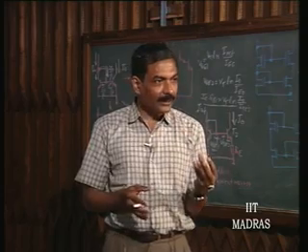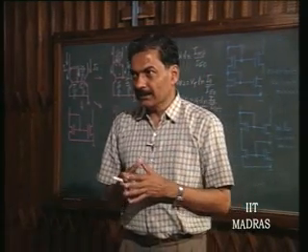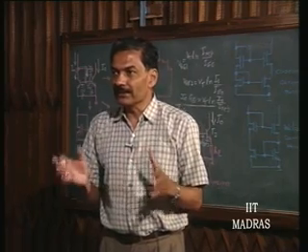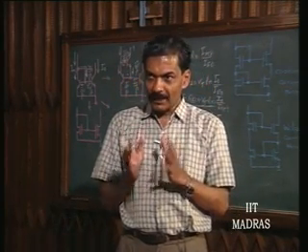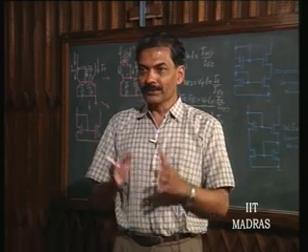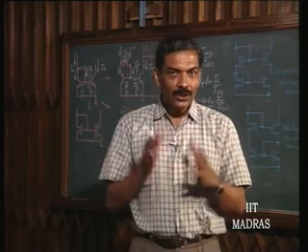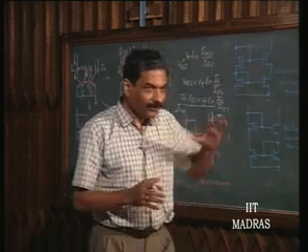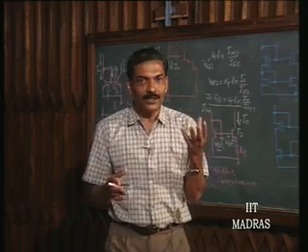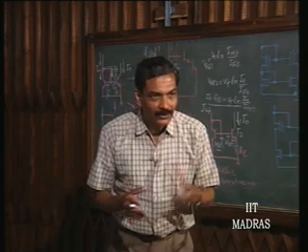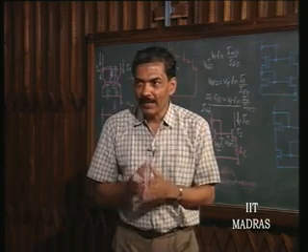We have already seen that our transistor ICs do not prefer large valued resistors. In order to therefore develop low valued current for biasing, we cannot use resistances of the order of mega ohms. So, in this particular case, without using resistances of the order of mega ohms, using only resistances of the order of kilo ohms, we are going to design a circuit for low valued currents.